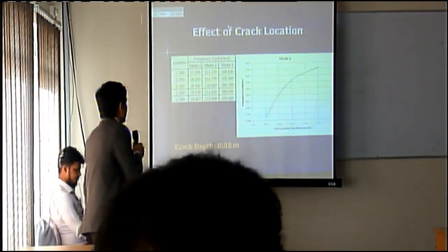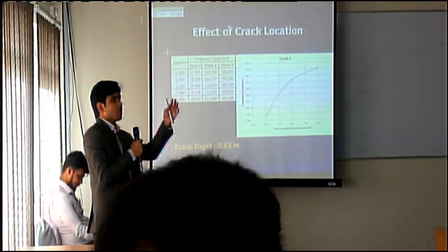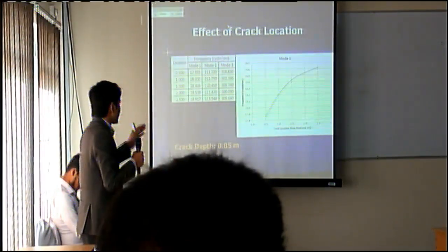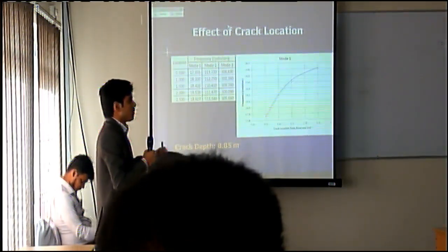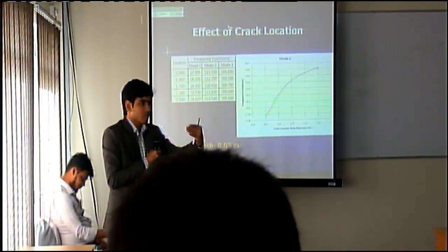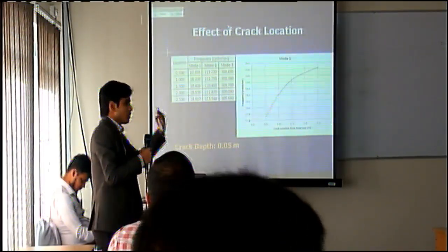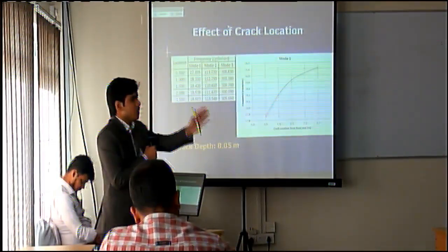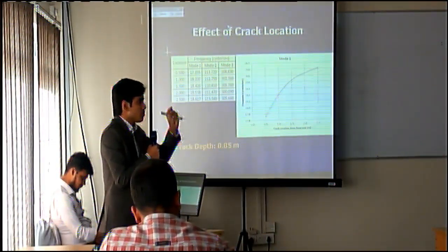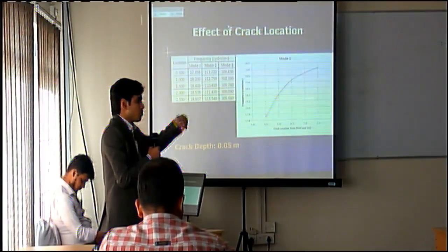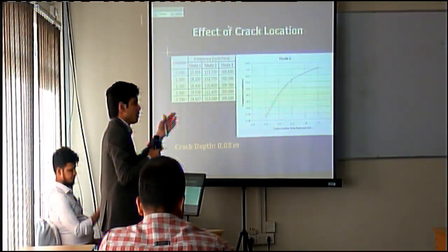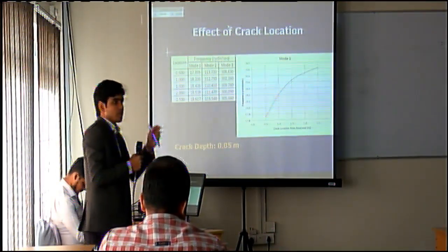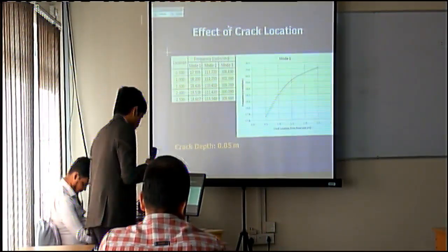Now the effect of crack location. If the crack is located near the fixed end, the reduction is maximum. If the crack moves away from the support, the effect is reduced. That is, if the crack is located at the free end, then the reduction of frequency will be less. It is somewhat equal to the uncracked beam. But if the crack is located nearer to the support, then the frequency reduces more.